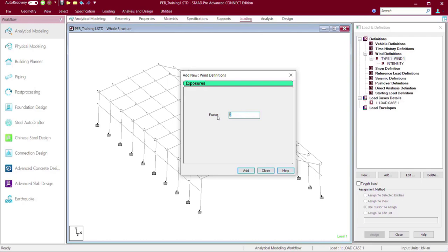So effectively, the entire area has been reduced. So we can't take the entire area for calculation of total wind load because the wind intensity is not falling on this entire area. So my effective area, which is exposed to the wind load, has been modified, right?